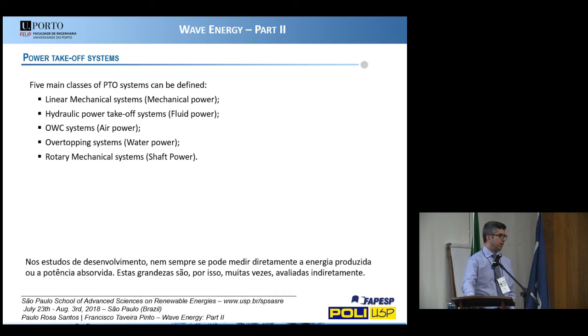Essentially we have a floating body with, let's say, a hull with the gyroscope inside, and so the waves induce some motions of the floating platform, of the hull, and those motions have energy that goes to the gyroscope. So the oscillations of the floating platform also induce motions of the gyroscope. So the principle is more or less the same as in the previous case.